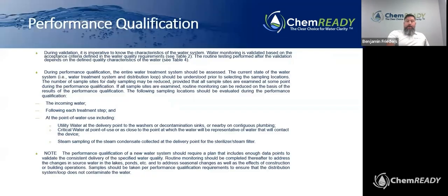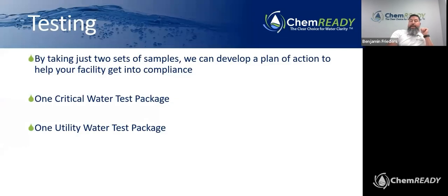That does not meet the requirements of this performance qualification. No, it does not. However, we don't know if you are compliant to begin with until we do 1 utility water test and 1 critical water test. And we propose those be after a softener if you have it, or at the city water, and then after all of the steps for your critical water system before it gets to your points of use.